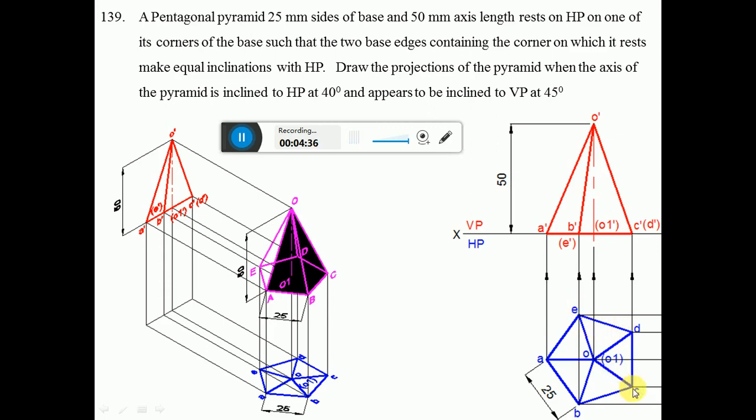by using the compass, measuring a distance of 25 mm, cut an arc on this. Similarly, with D as center, with a radius of 25, you cut an arc on this to get the points B and E. Similarly, with E as center, draw an arc, and with B as center, cut the previously drawn arc for a radius of 25. Then you mark this point as A. Then join A to B, B to C, C to D, D to E, E to A, which will be a pentagon. Then you need to find out the center.